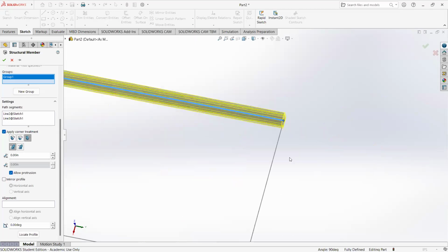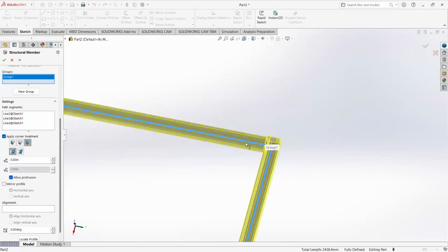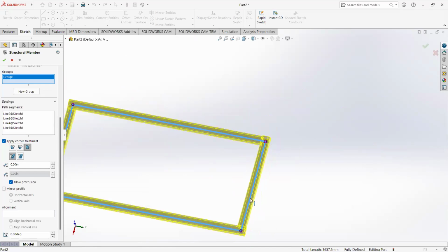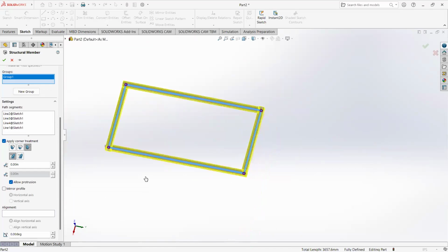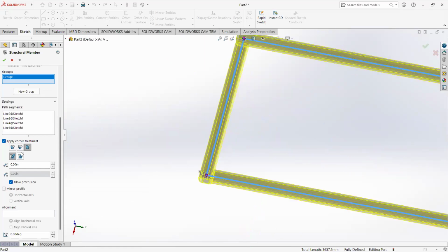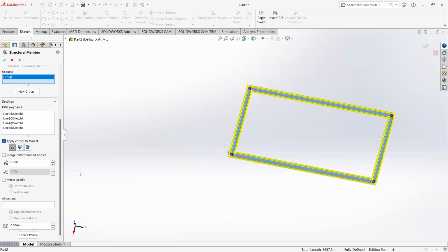So if I come now and select the rest of my rectangle, again, since this top line was selected first, it's the one that gets cut short. The right hand now got cut short, and this one stops at the first one I selected. So we can flip between them, select here, right? It pops that preview back and forth. I'll miter it, because miter is kind of good.